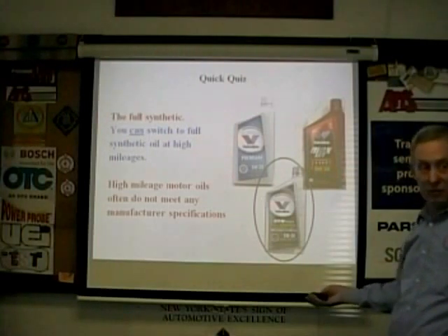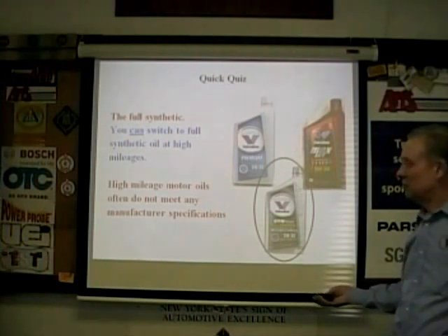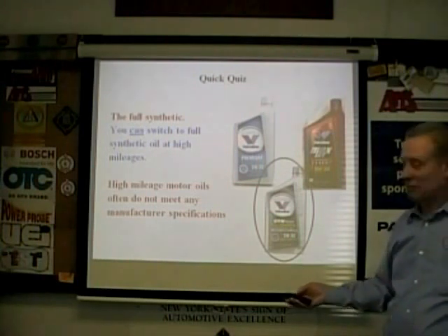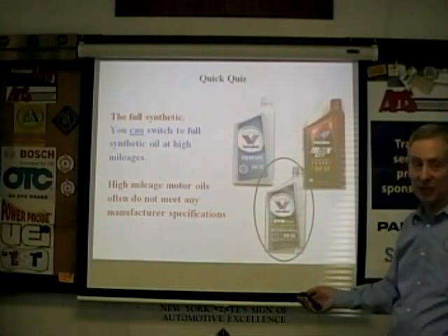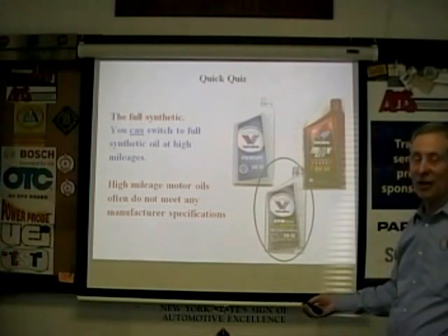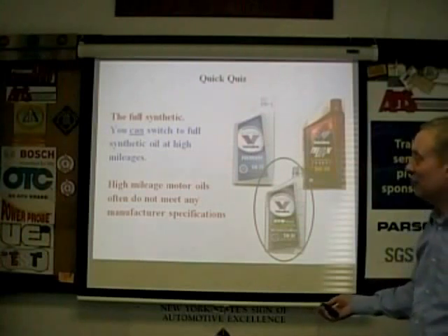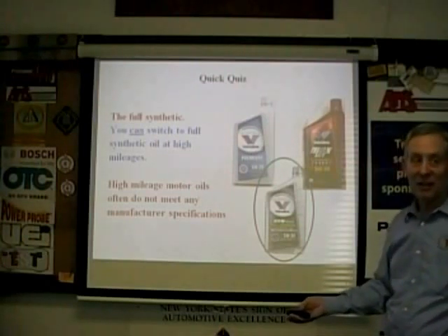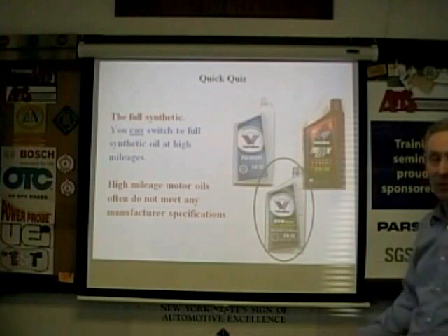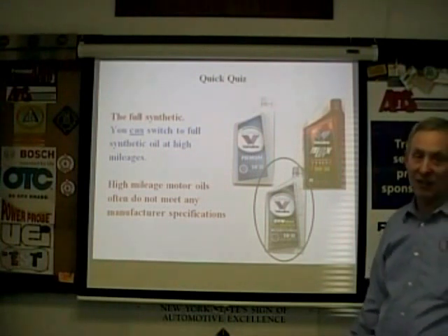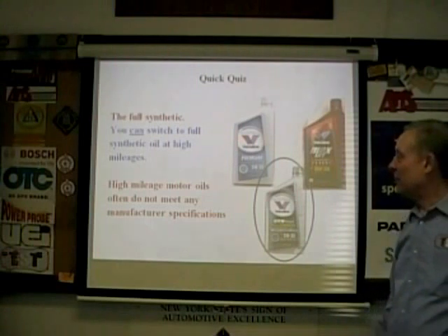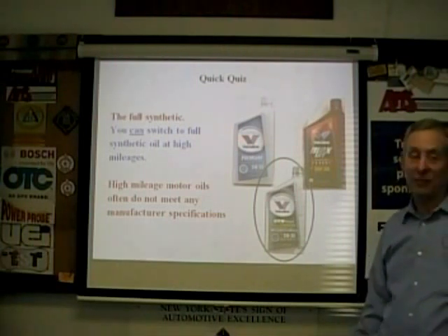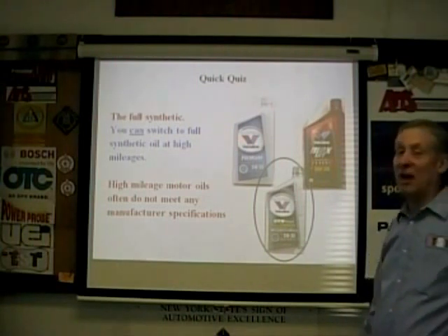Is it true that you cannot change from synthetic to regular, or vice versa? That's actually a bit of a fallacy, but there are some risks involved. It used to be that if you switched from regular petroleum oil to synthetic on a high mileage vehicle, there was some conditioning of seals going on and they would leak like sieves. I don't think that's true anymore. But you do have to watch going back and forth. Again, read the specs. I would recommend not doing that.